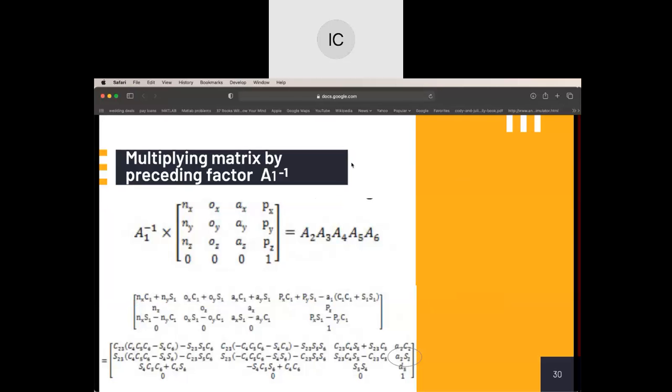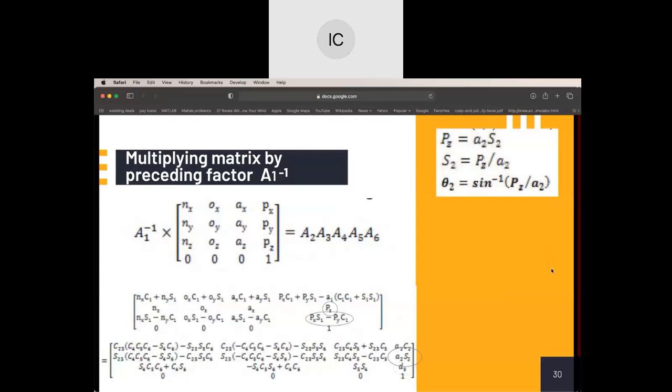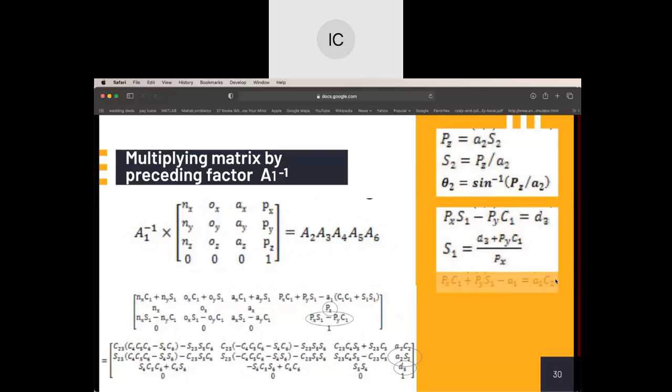So to separate the angles, we're using that RTH matrix that we previously saw. It's going to be pre-multiplied with the individual inverse A1 matrices. So we're calculating the value of each angle using the end effector position, which we went through earlier and can be seen here in the second matrix. I circled the values here on the slide that we're calculating on the right hand in these equations. And as you can see, we can solve for theta 2 as well as theta 1 down here.